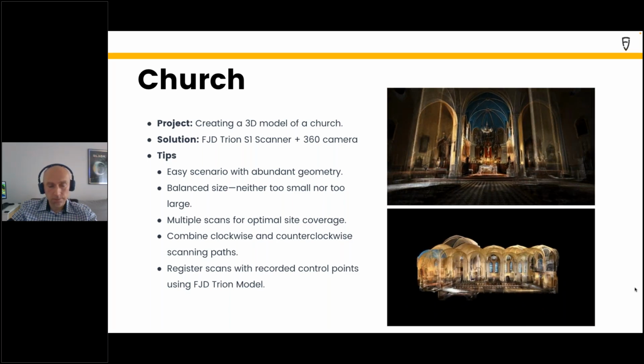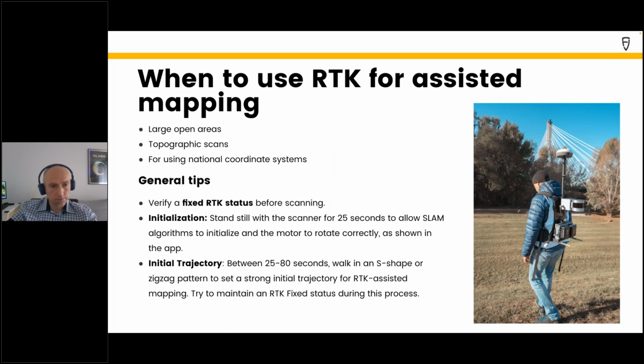Please, next one. Okay, this is me wearing a backpack solution for RTK assisted mapping. You can read some basic rules for this. I will add one more thing. Keep in mind that you generally scan objects behind you. So if the scanner is on your back, you have to really think about your scanning path again.